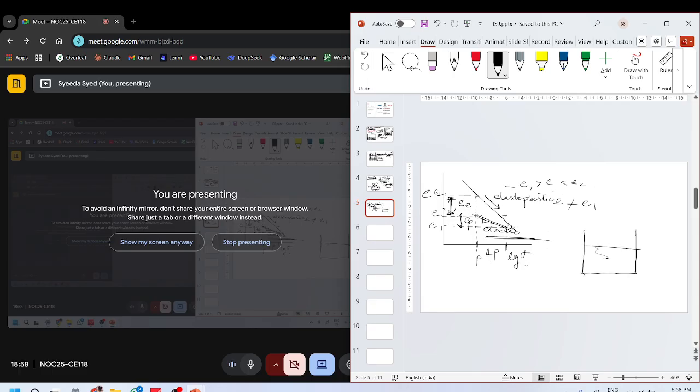If you loaded the springs here and you had a porous material here, now when the springs want to release, water has to move inside, which is the negative of what we were doing. So we will have a negative pore water pressure. So I would rather that the analogy be taken only for loading, not for unloading.